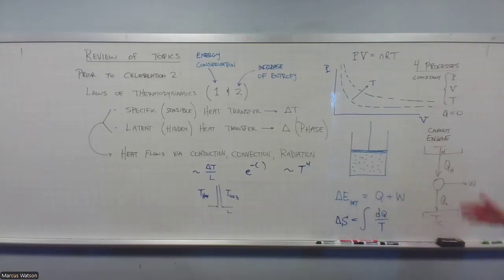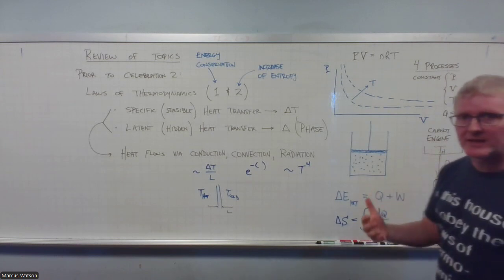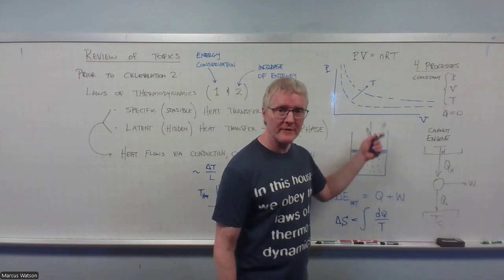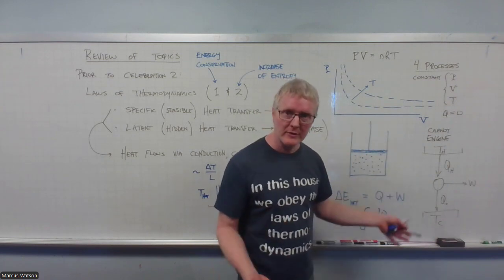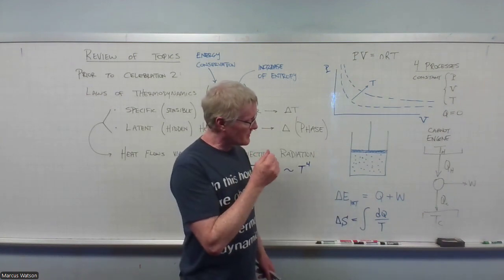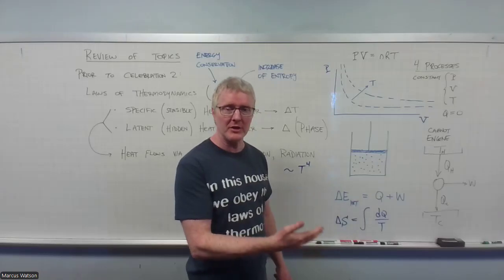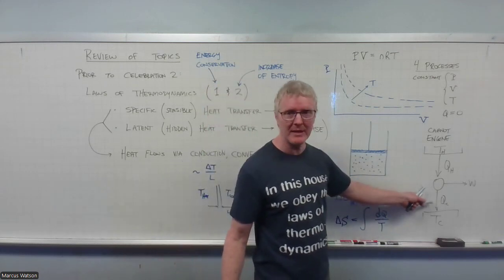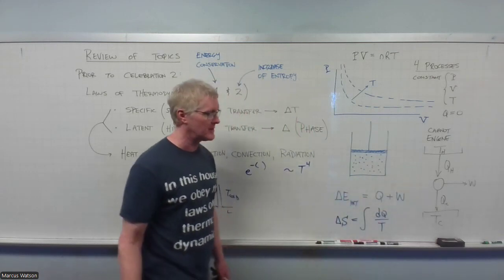In which I have a hot reservoir, a cold reservoir, and some type of piston cylinder, and I'm working that gas around based on the heat that I'm putting in and the heat that I'm dropping out, and hopefully it ends up doing some net work for me. Thinking about the Carnot efficiency, and then regular efficiency as it relates to the entropy, gives us a way to figure out how big the QC is going to be in these cases, right? Because part of the argument is you can't make QC equal to 0 in these cases. That's part of